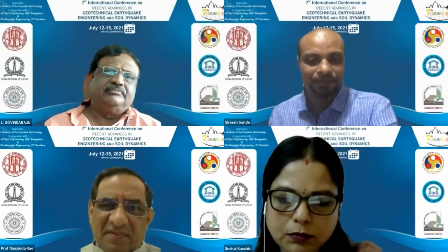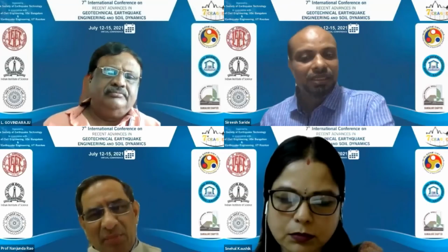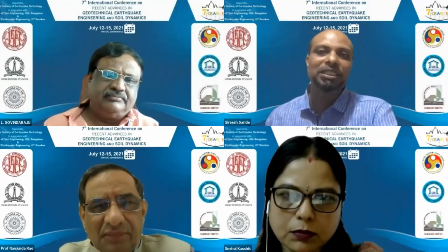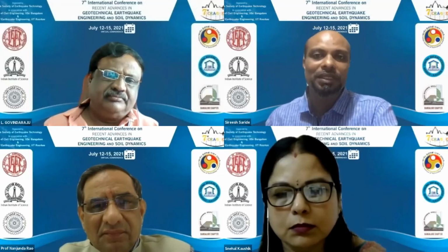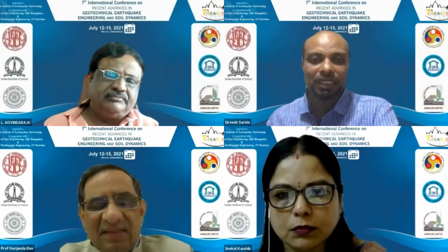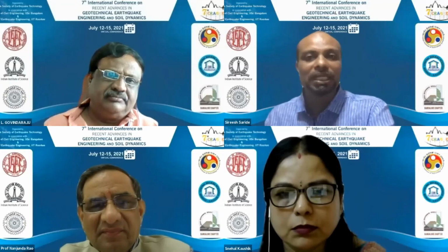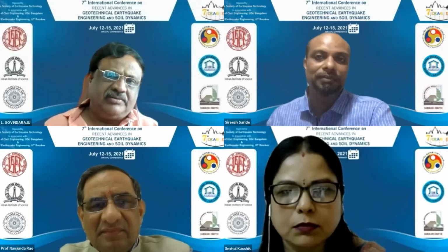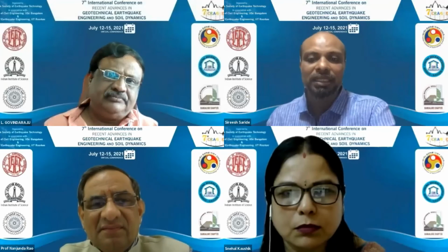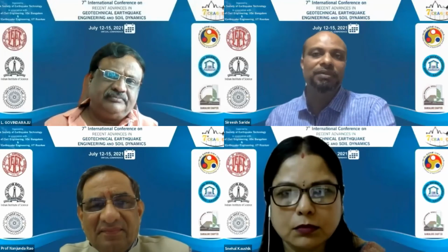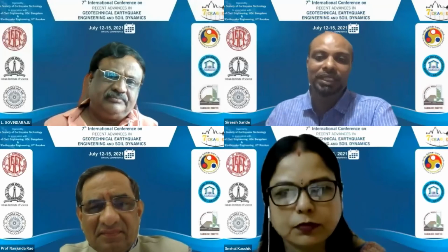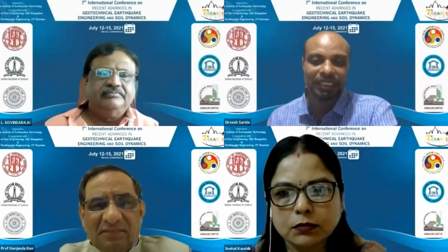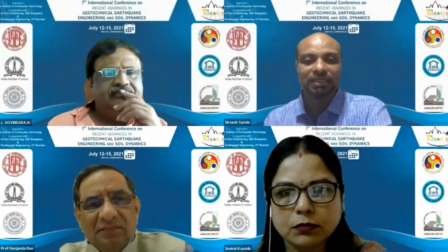Did you try anything with a hybrid like GGBS? Yeah, that's another combination. Fly ash and GGBS can be used because their silica and alumina are highly reactive. In this case, with the low calcium fly ash that we have used, the silica content available is not in an amorphous state. Most of it is crystalline. So a very limited amount of silica was ready to react. So we need to supplement silicates using water glass or sodium silicate. That was the reason we had to add a combination.